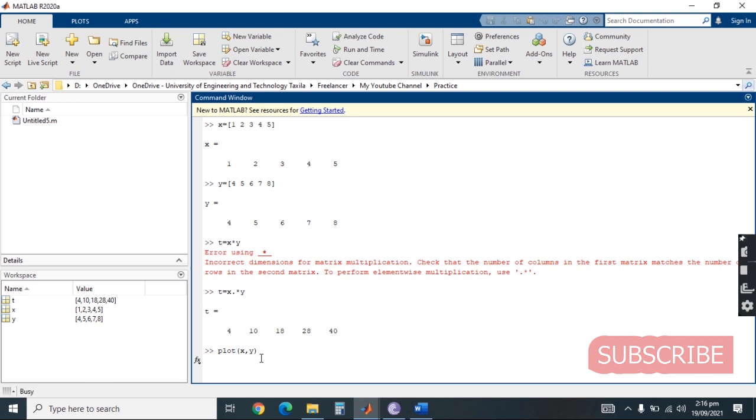Now we will move toward the plot statement and draw some basic plots. Plots can be drawn in MATLAB by using the plot statement. The first element in the plot x, y statement represents x-axis data while the second element represents y-axis data.